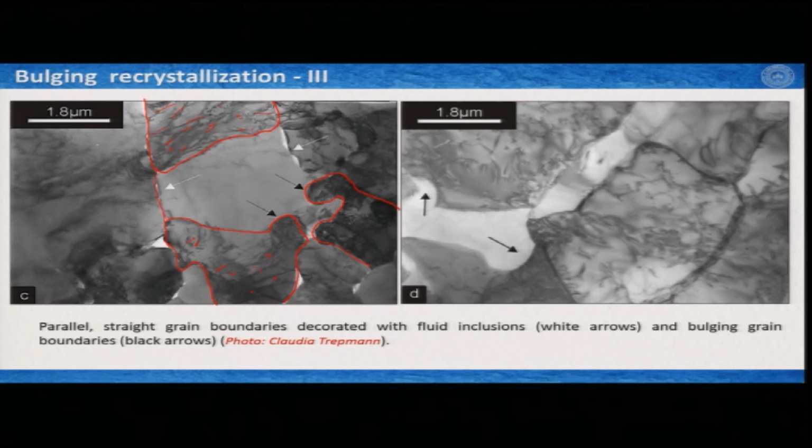All these tiny little things here are also dislocations. But this grain in the middle has much less dislocation. So you can see that a grain with less dislocation density is surrounded by 3 grains with higher dislocation density, and interestingly some sort of bulging has happened here, where this grain with low dislocation density tried to bulge or invade within the grain where dislocation density is much higher.